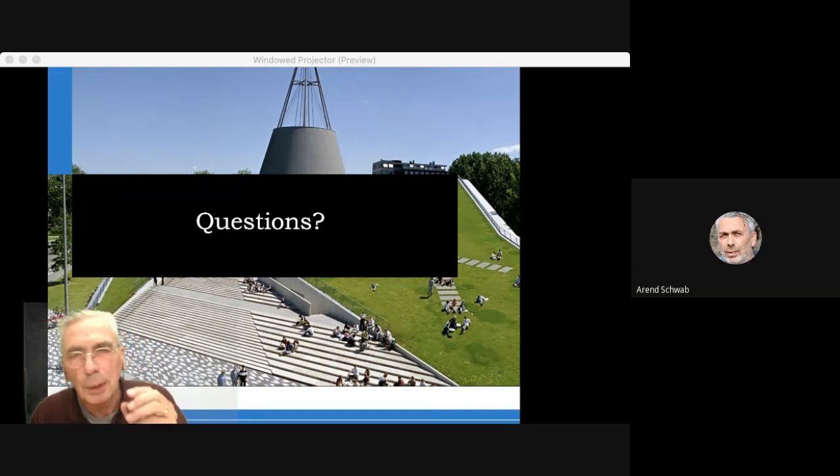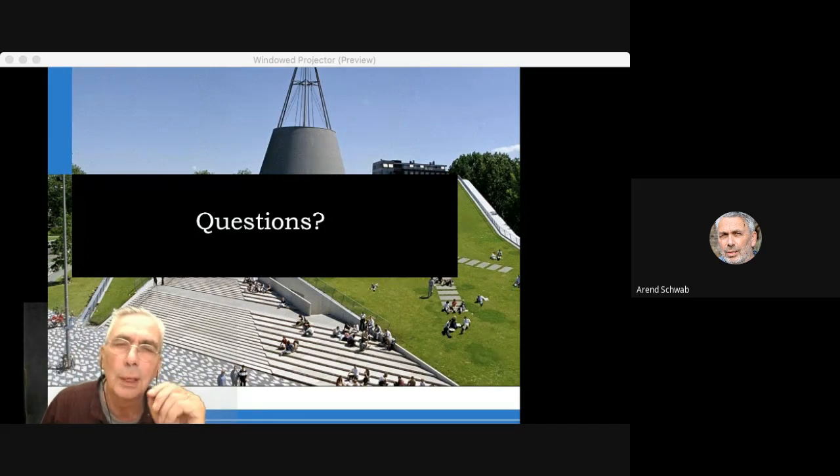And we also made the trail zero. We even made it a little bit negative. So the contact point is a little bit in front because in reality, you also have, of course, a finite contact region. So we wanted to make sure that the net lateral force is not still behind the steering axis, but it was actually a little bit in front.